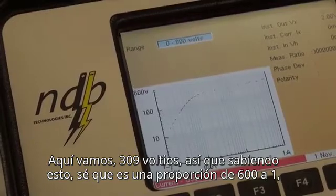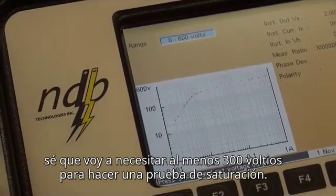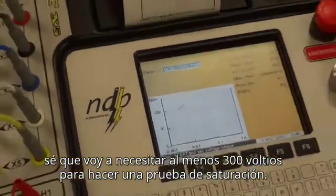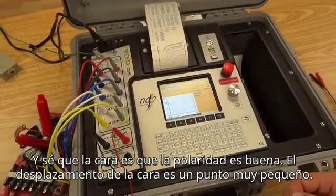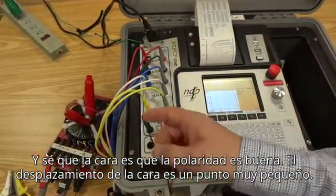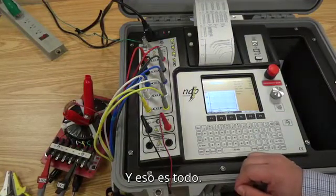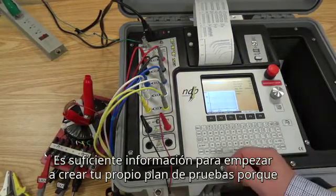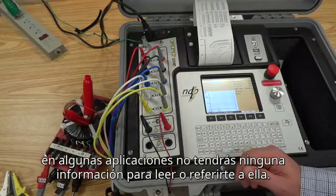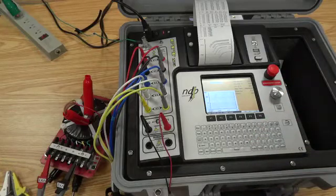So, knowing this, I know that this CT is a 600 to 1 ratio. I know that I'm going to need at least 300 volts to run a saturation test. And I know the polarity is good. The phase shift is very small, 0.2. And that's it. That's enough information to start creating your own test plan, because in some applications you won't have any information to read from or refer to. And this can help you out and get you out of trouble.